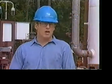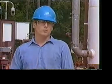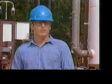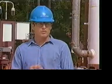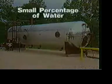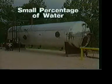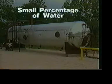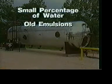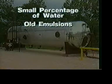Several factors determine how easy or difficult it will be to break an emulsion. Some factors are the type and amount of emulsifying agent and the conditions under which the emulsion was produced. Let's look at some of these factors. Generally, emulsions with a small percentage of water are more difficult to break. Old emulsions die hard. The longer an emulsion remains untreated, the harder it is to break.